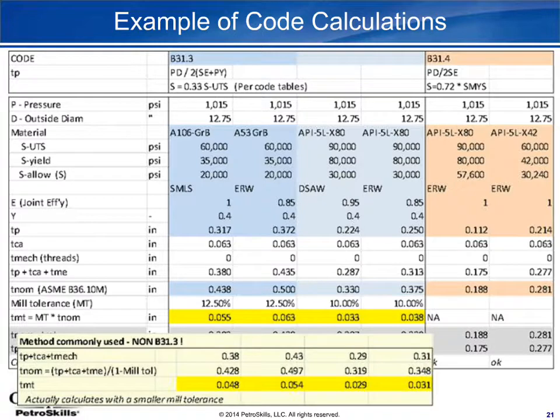When I'm doing plant fabrication at cold temperatures, I will need to be cognizant of the construction temperature, because a similar situation occurs from what we call expansion stress, meaning we construct at a cold temperature and then we actually have to operate at a higher temperature. In B31.3, well, actually all the codes say that you have to do some kind of analysis if expansion stress is excessive. It doesn't say when. B31.3 gives you some guidelines in terms of a flexibility analysis, because you evaluate the change in temperature results in a certain amount of strain.